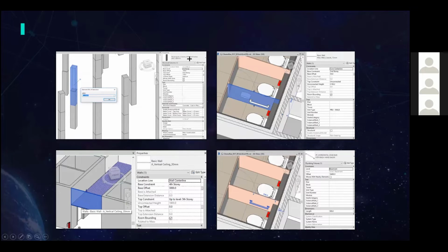If you go ahead with a rectangular column without finishes, this is the size, that's the type of it. But then it's running throughout the building. We don't want that. Similarly, with the basic wall, when you select it, it's going a little bit inside there and creating an L shape, but that should not be the case. It should be a separate element. So always pay attention to the details of which element should be what. That's basically the modeling principle.